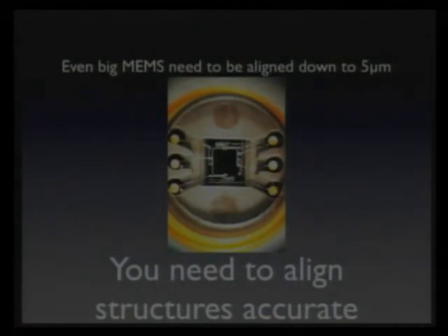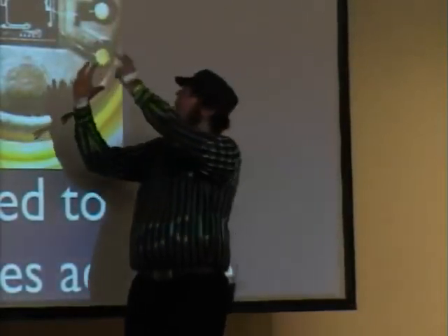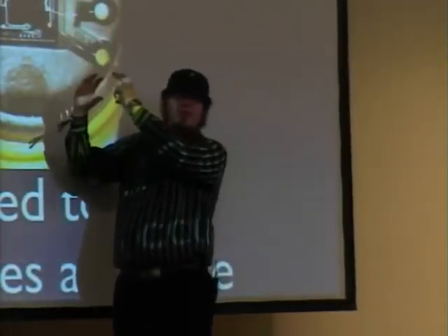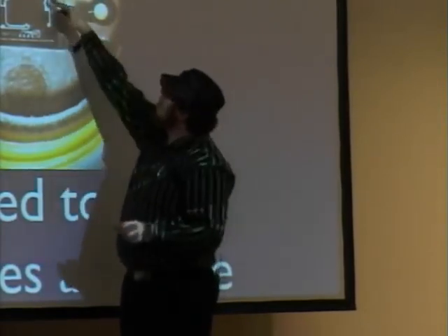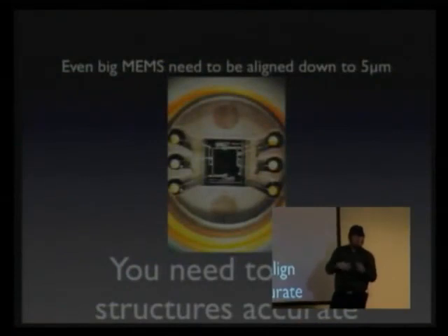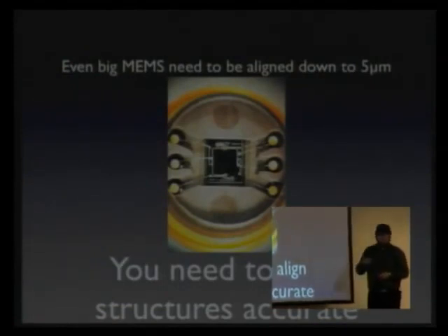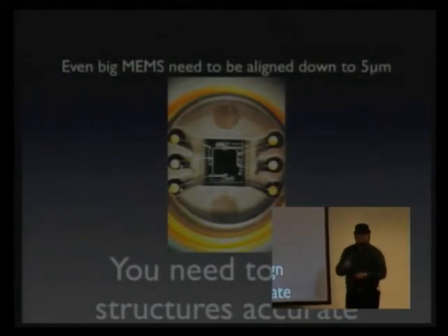This is a very old-fashioned pressure sensor. So you have the membrane on the backside and you etch from the backside, so you have to align here your connection structures to the backside, which is already a problem. And then here you will have small dotted areas, like with imprinted ions, so that you get more or less electrodes in there, depends on what you're doing. And you have to connect them with the accuracy of repeatable 5 microns, which is really a big problem when you try to align this by hand, for example.